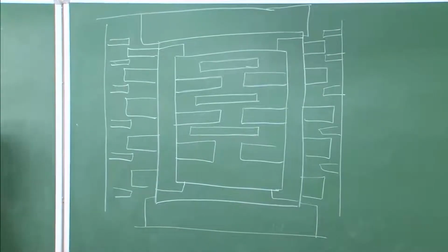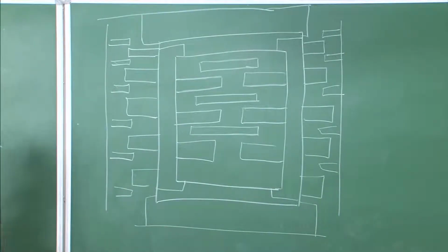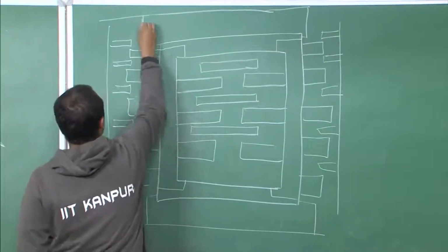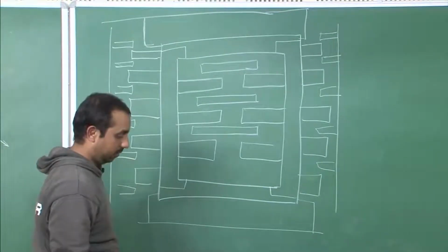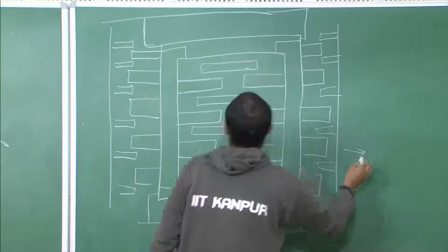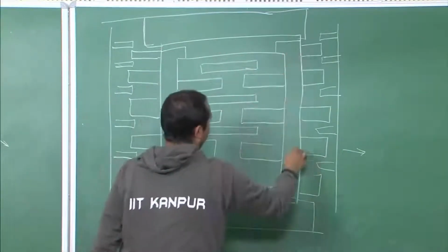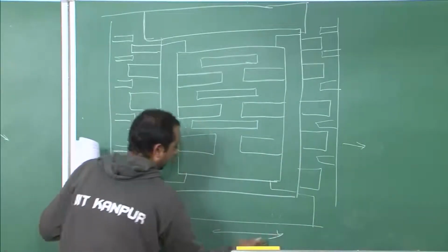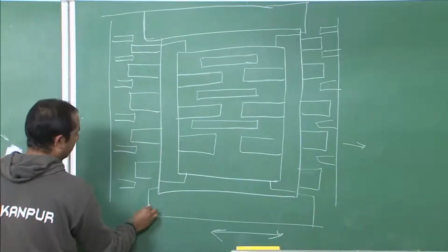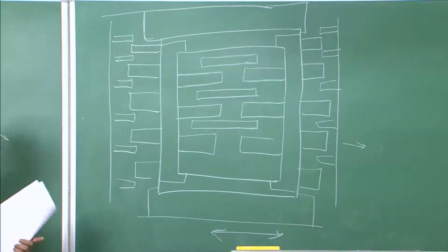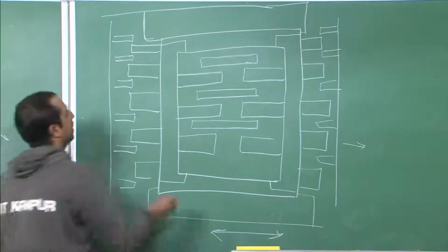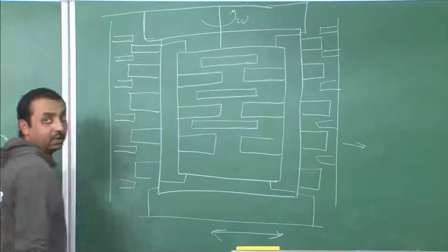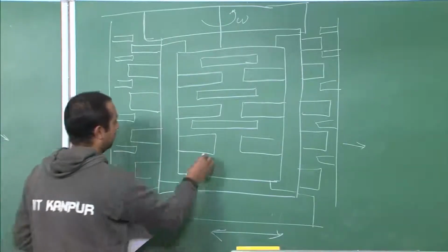Now when the body is not rotating or it doesn't experience any angular velocity, the movement will be with this. Suppose your body is moving in this particular direction, so your outer casing will be moving in that particular direction, that is oscillation will be in this particular direction, either this or this outer case will be moving. Once it experiences angular velocity, say about this axis, this particular inner casing will be moving.